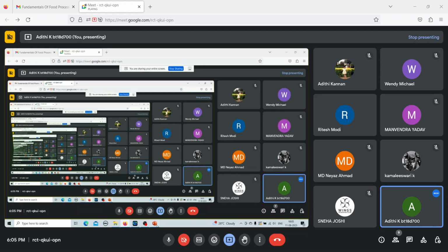So hope this is clear. What is Biot number and why is it necessary for it to be less than or equal to 0.1? Lump parameter analysis assumes the internal conduction to be 0. So ideally Biot number should be equal to 0, but in real cases that is not possible. So we assume less than or equal to 0.1.